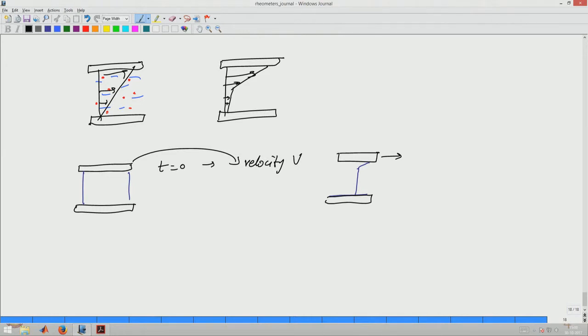So, that is the difference, but again at steady state, what you would see is generally, provided the shear stress being applied is higher than the yield stress, you will again see a linear velocity profile. But how do you know that it flows fully? That depends on the velocity with which you are applying, and therefore what stress is being applied on the material.